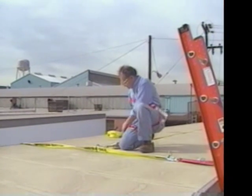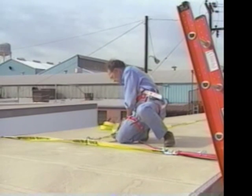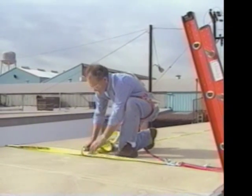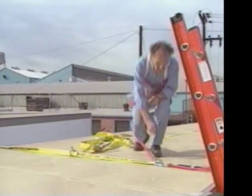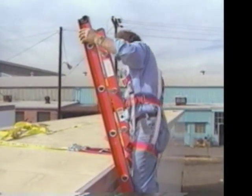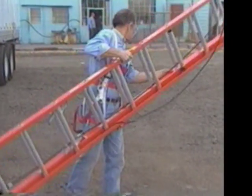Once your job task is complete and you are ready to return to the ground, switch the lanyard from the D-ring on the center strap to the D-ring on the cross strap nearest the ladder. Loosen the center strap and move to the ladder. Once you are on the ladder, disconnect your lanyard from the cross strap's D-ring and untie the ladder. Return to the ground and remove the ladder.